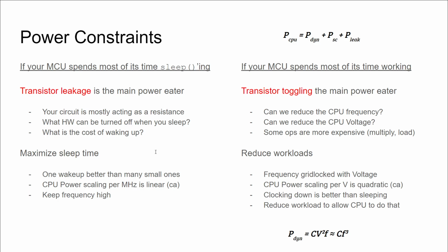So if you can achieve that, great, we can reduce the clock frequency until the CPU workload is just short of a 60th of a second. And you can, in the ideal world, configure your DVFS system to take that workload as some input and scale the frequency down accordingly. And this makes a substantial impact on power usage.